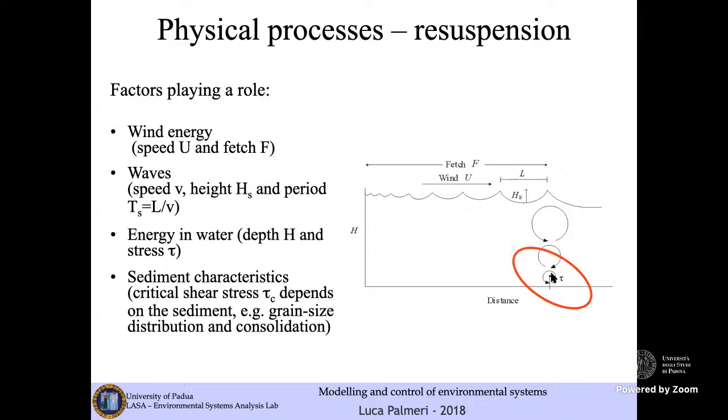Please note that the shear stress translates the energy of the wind through the waves and through the vortex induced by the waves, but while you are traveling toward the coast, so toward lower depths of the water body, the effect of this force, of this energy, is greater.